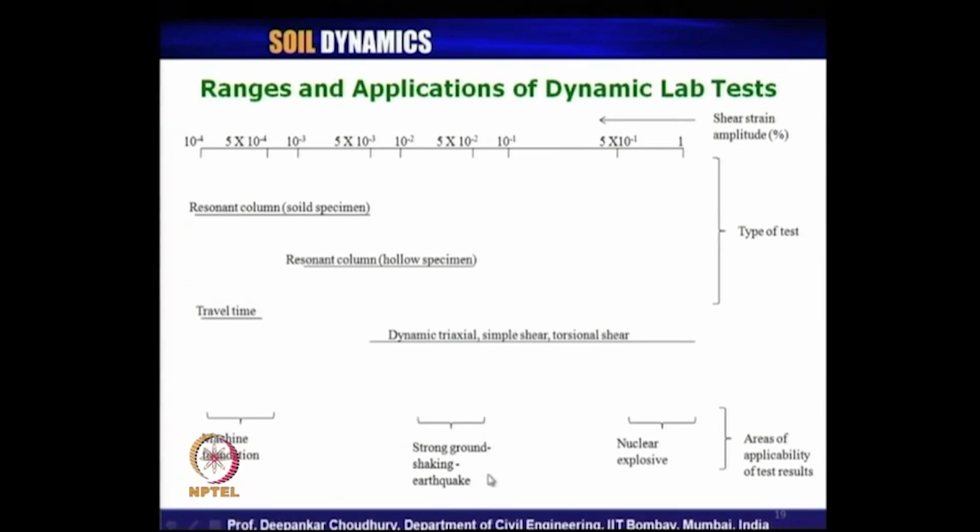Using that for earthquake analysis is most of the time questionable. So, you should not only have an estimate of Gmax through the Vs value from a field test, but also do a cyclic test on your sample in the laboratory. Better to use triaxial, simple shear or torsional shear with cyclic loading.